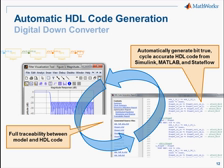We discussed how we then worked with a hardware implementation model that included design refinements intended to improve the FPGA implementation in Altera devices. We showed how the HDL Workflow Advisor steps us through the HDL code generation process, from choosing a target FPGA device, through preparing the model for code generation, and ultimately for targeting the design to the Altera Quartus II implementation tools. We also saw that Simulink HDL Coder produces very readable HDL code that can be traced back to the Simulink model from which it was generated. And finally, we showed how further refinements and optimizations could be made in an iterative design process.